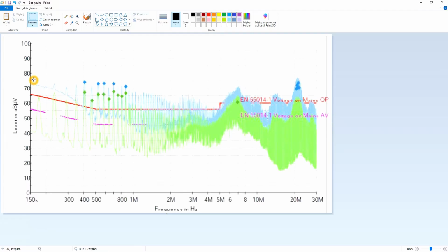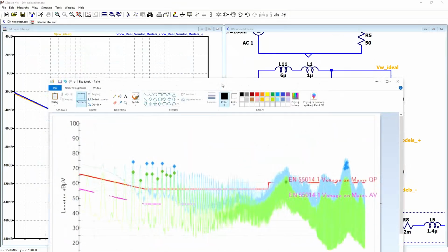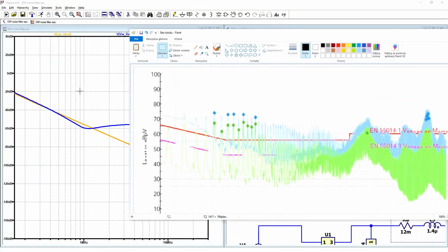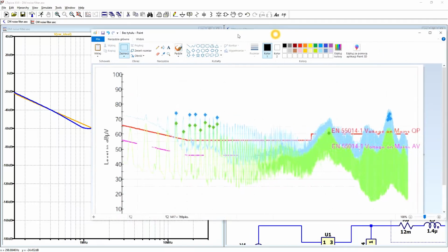also include derating of your components. So inductors for higher current will have less inductance, and capacitors also derate with the voltage. So we need to have some higher attenuation to include derating. So for example, if we have -20 dB, that could be not enough, and we should include more attenuation. And we can do that by adding more inductance.